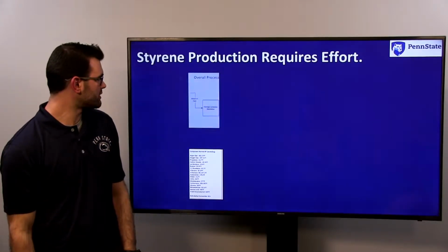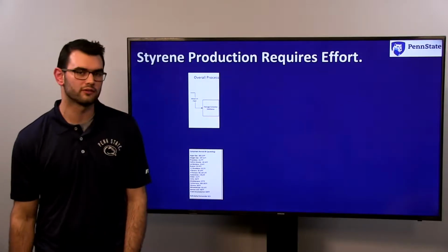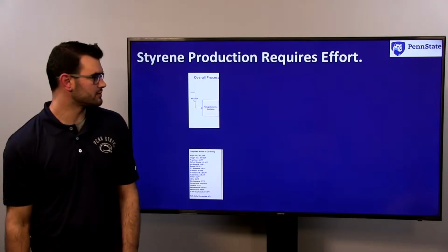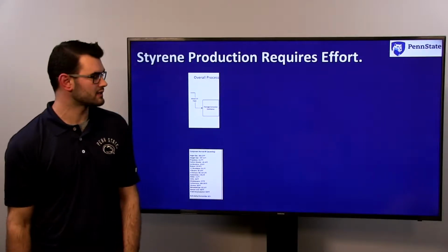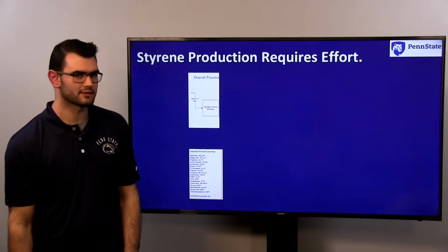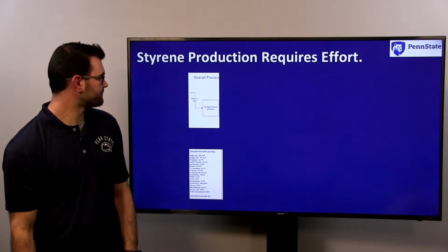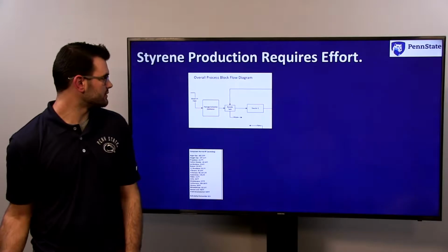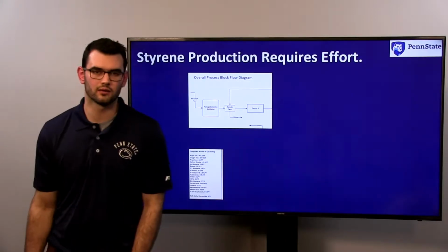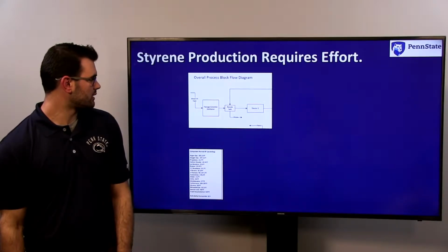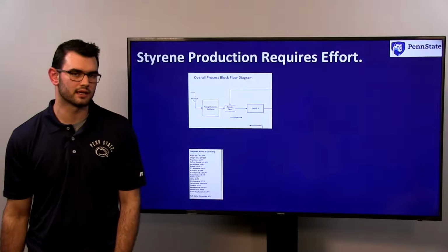We have 1,3-butadiene coming in from an olefins plant mixed with other C4 components. We found it to be easiest to send this through an extractive distillation unit to capture the high purity butadiene as our first reactant. This stream is sent to a recycle, which I'll get to in a minute, where it's combined with a lower composition of butadiene.